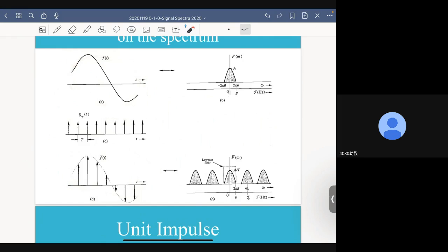By inspecting these two curves, we cannot have any idea. But if we switch our attention from the time domain to the frequency domain, what we want to do is measure whether, after the sampling operation, the frequency contents of the original signal can be preserved. If they have identical frequency contents, then it means they carry identical information.